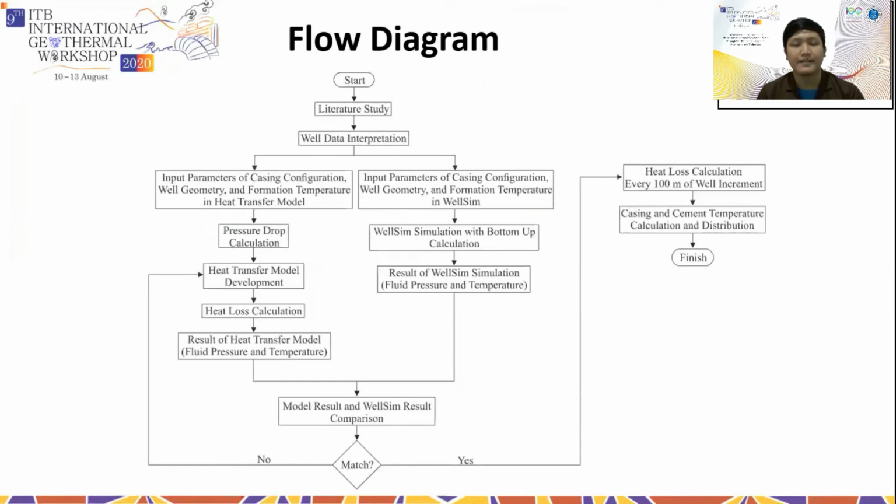And then for the WellSim calculation, we start with input parameters. Those parameters are similar to the parameters that we use for the heat transfer model calculation. Next is the calculation with WellSim simulation with bottom-up calculation, and we will get the fluid pressure and temperature from the WellSim simulation. Next is the comparison of the model result and the WellSim result.